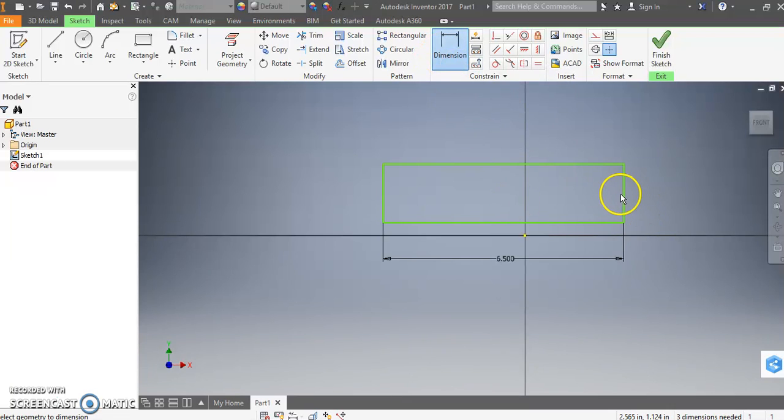Now we'll use the dimension tool to select the side of the rectangle, move to the right, and enter our height. Based on the sketches that you did of your cars, our height is intended to be 1.5 inches tall. Now, we have the rectangle, which represents the side of our vehicle. It is 6.5 by 1.5. At this point, we've finished everything that we can do in the sketching view. We're creating just the rectangular prism that will make up the block of our dragster later on.